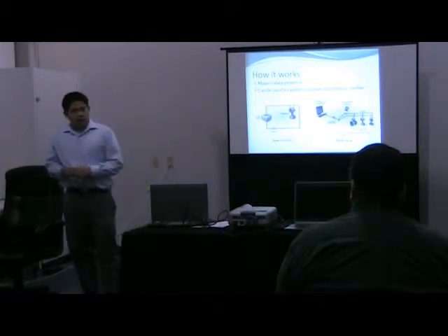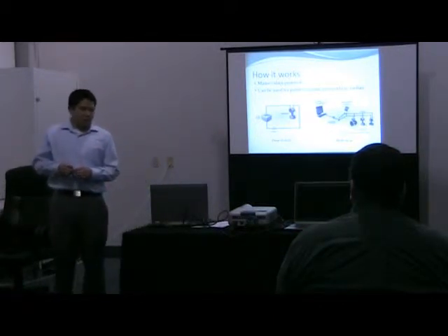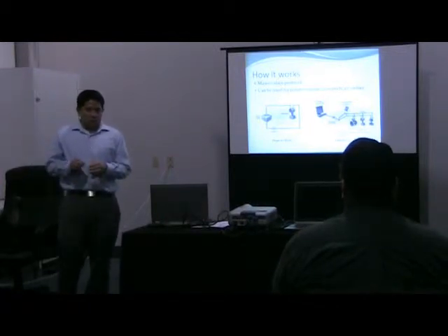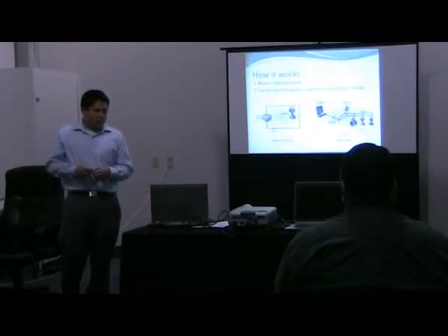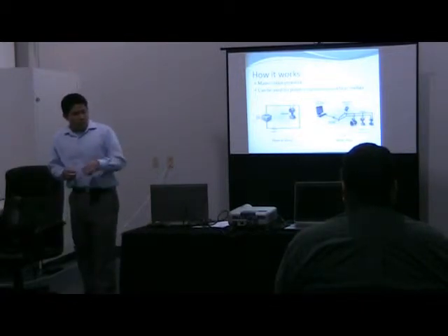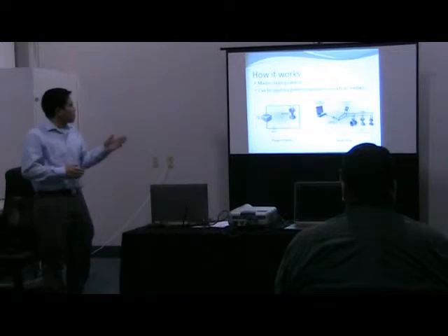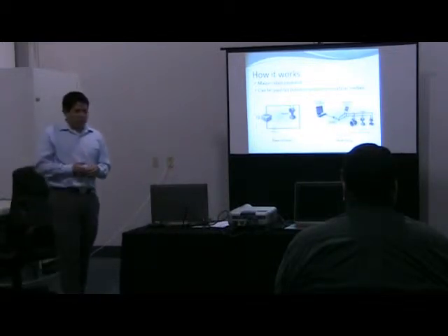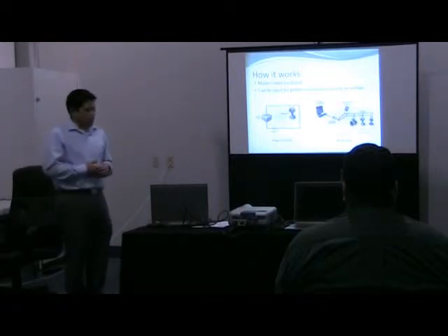HART is also a master-slave protocol. So basically, your slave device, such as your instruments and things like that, won't speak until spoken to by the master. And it can be used in 2 common configurations, which are point-to-point and multi-drop. But for the purposes of this demonstration, we're just going to be focusing on point-to-point.